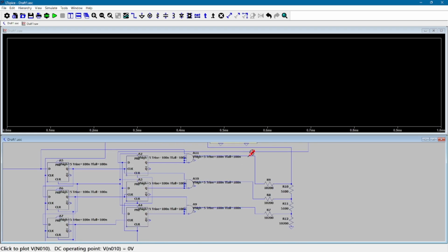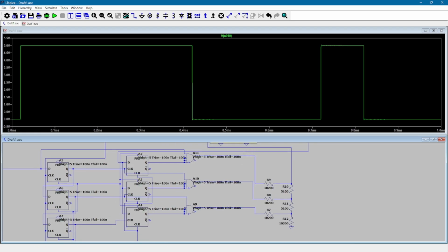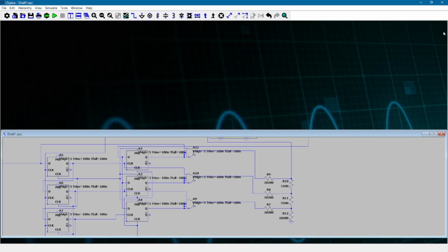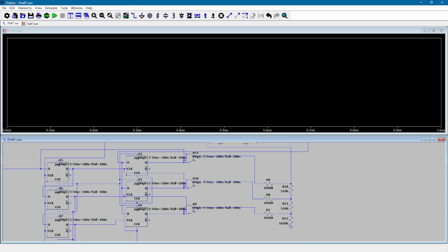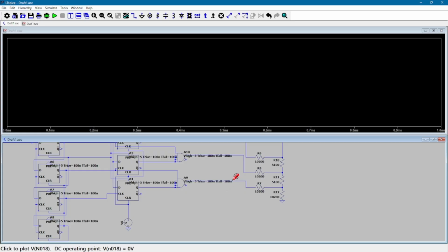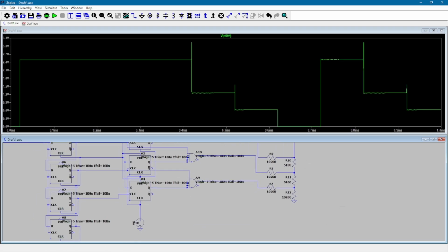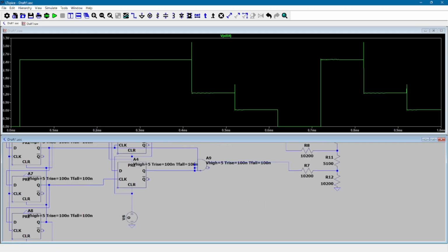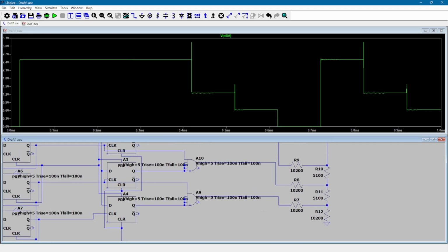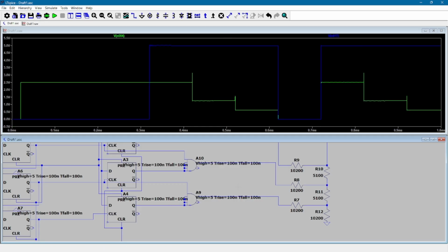So, let's step over. Let me just rerun that. At the very first step, at A4, the DAC outputs 2.5 volts. It's a little hard to see, but yes, the first output is 2.5 volts, which is fed into the comparator. Since 3 volts is greater than 2.5 volts, the comparator sends a high into the register A4, which then latches a high, or I guess a 1.